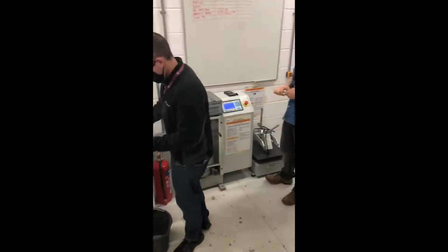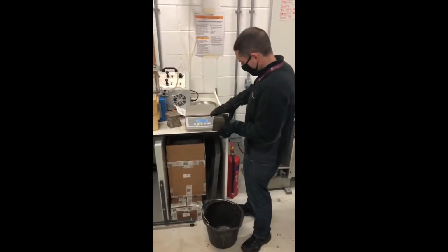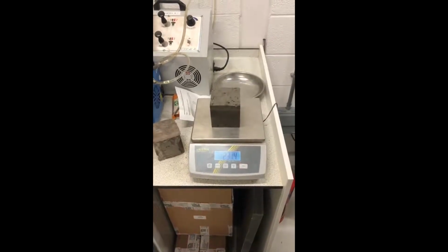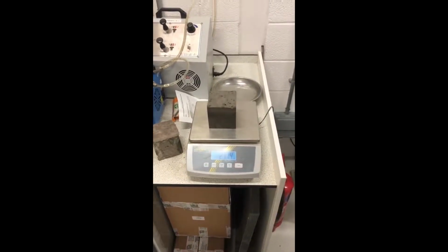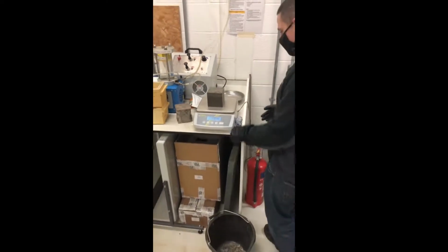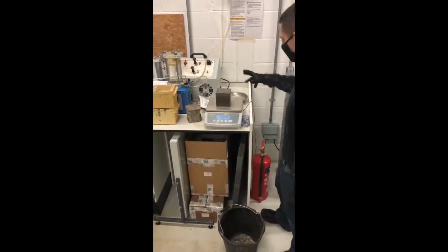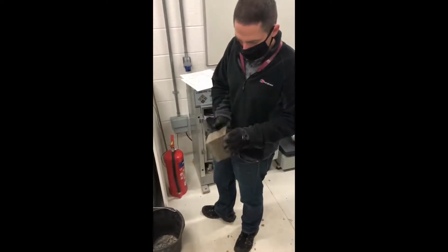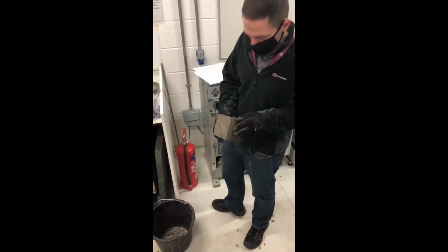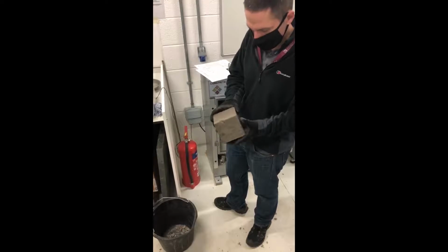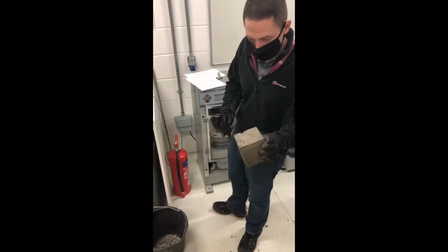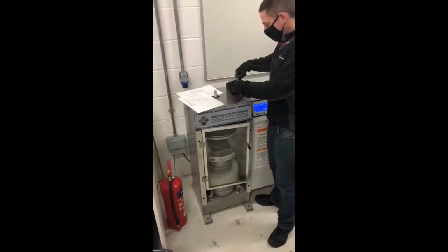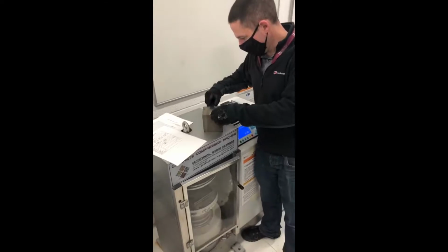So this is cube number 2. The mass of cube 2 is 2.314 kilograms. And again, check for any defects, but everything seems to look okay. There's nothing glaringly obvious, any cracks or deviations in the surface. So what we'll do again, we'll just measure the dimensions to make sure they're compliant with the standards.